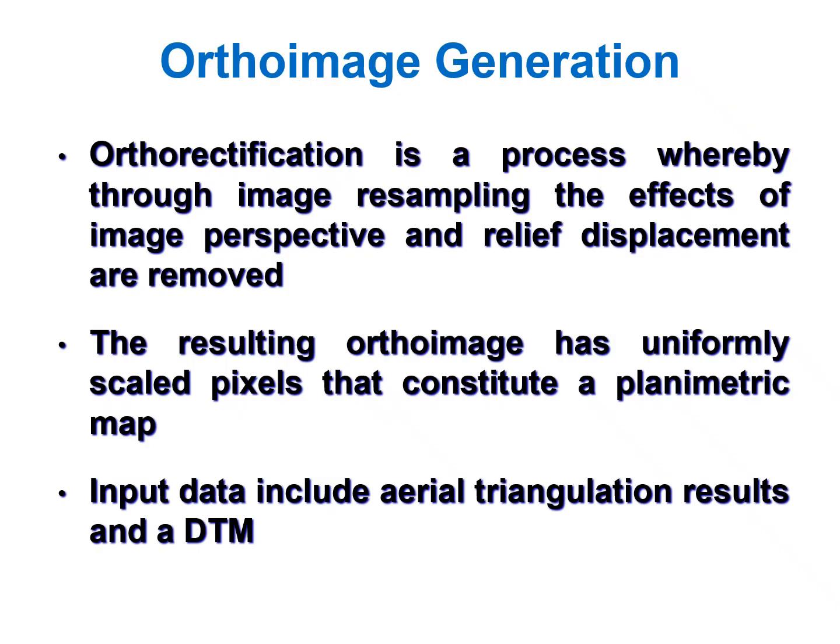Ortho-image generation. Orthorectification is a process whereby, through image resampling, the effects of image perspective and relief displacement are removed. The resulting ortho-image has uniformly scaled pixels that constitute a planimetric map.